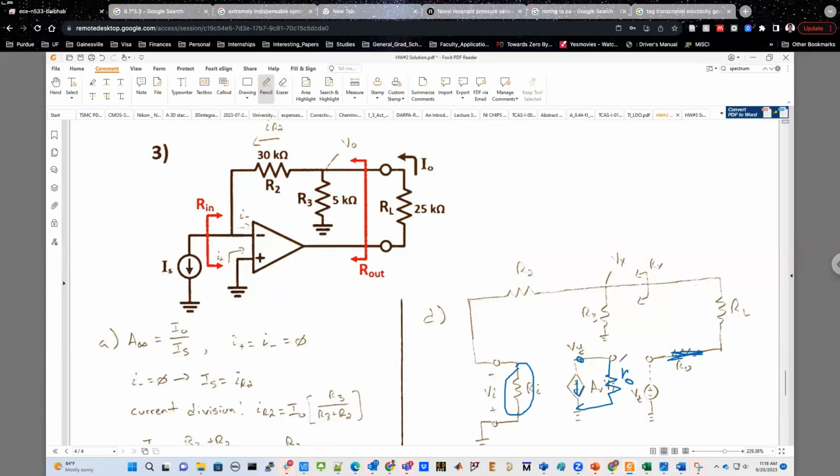Do similar calculations of voltage division across all these resistances. Eventually you'll find a voltage at the input side, right? And you can call your feedback factor the voltage that gets developed across Rin divided by the voltage available at this point. That gives you your feedback factor.